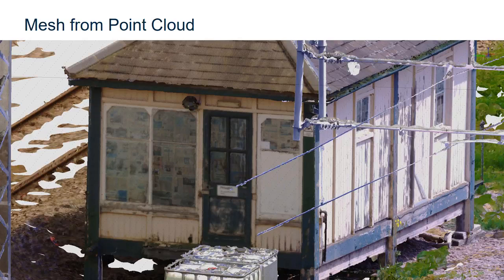Here I'm showing you exactly what a point cloud looks like. As I said, they are just dots that are floating in space. These do have color codes, which were produced by the scanner, which is helpful for us to tell the difference of one dot next to the other one. But we're still seeing things like the grass through the building, which makes it really hard for me to understand what the front of the building is, the back of the building, since we are able to see through this.